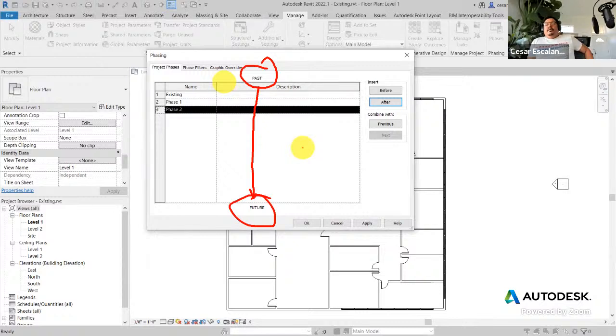If you're not part of the BIM lead organization, then demand that you understand what the phases are, because once this is set, it's a strategy that all the consultants need to apply. The architect cannot have 2 phases while the consultants are only showing 1 or 2. This is more than Revit; it's a project strategy, a BIM execution strategy, and it usually gets documented as part of the BIM execution plan.